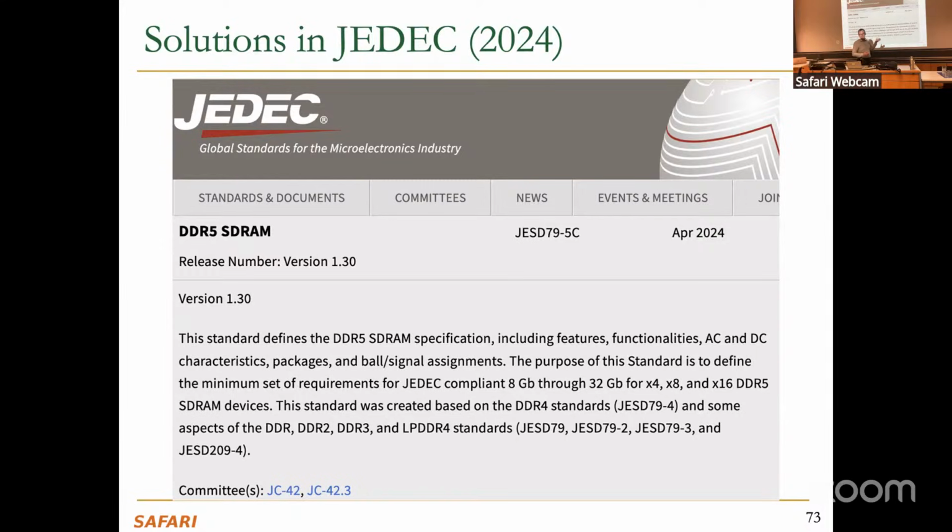One of the issues here is that at some point, the DRAM chip needs some more time to do mitigations, right? Because if you think about it, this is an in-DRAM solution. Inside the DRAM, there's some tracking going on in terms of activation counters, and the DRAM chip needs to refresh some adjacent rows, but it may not have time to do that because of the tight control by the memory controller to the DRAM chip.